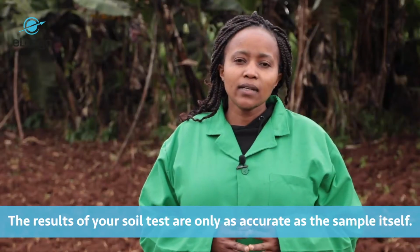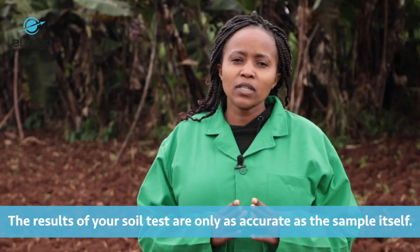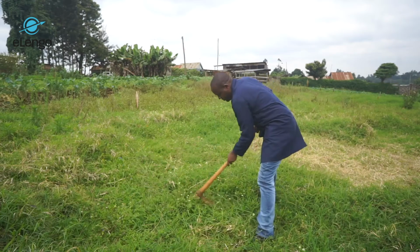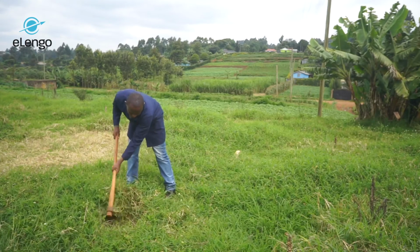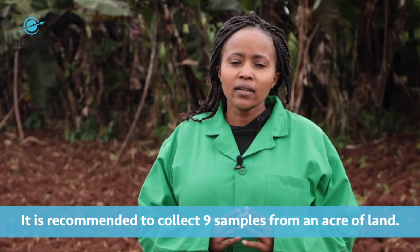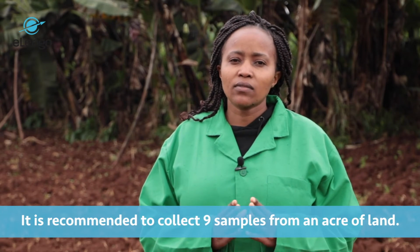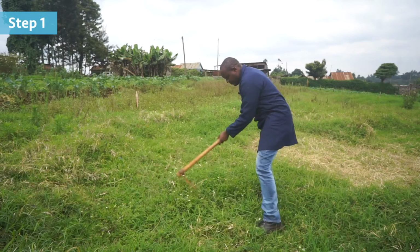In undisturbed land, the area marked for soil sampling should be measured and demarcated, and the surface vegetation removed. The number of samples to be collected will depend on the size of the field. Experts recommend about 9 samples in an acre of land. In this area, which is recently plowed using a jembe, and about half an acre, we are going to collect 5 samples.